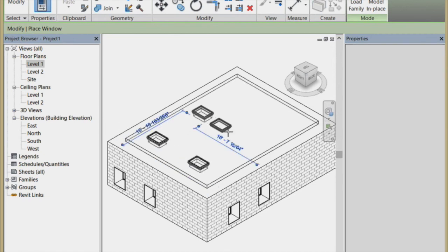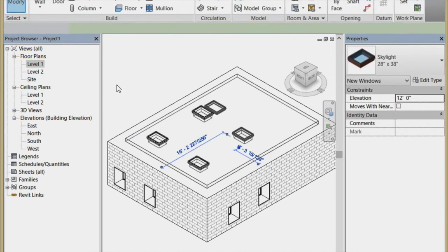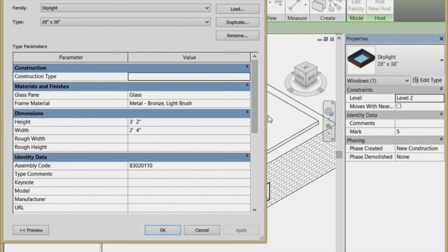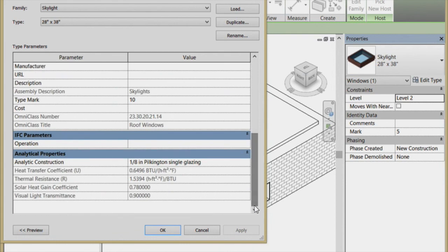They have all sorts of daylight advantages we'll talk about, but even they have thermal properties. If we go through and take a look at them, yeah, that's got to be, again, about a 0.64. Pretty much the same as a window, and that actually sort of makes sense. It's mostly glazing, it's mostly framing. In terms of the conductance, conductance doesn't really care a whole lot whether it's going up through the roof or going out through the walls. It's pretty much just a window, okay?